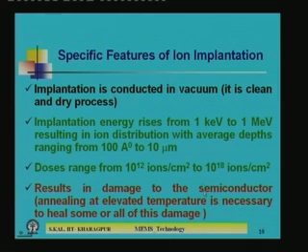During the implantation process, because of the damage, the material may be amorphous in nature. How do you know it? Just after implantation, if you go for measurement of the sheet resistance, you cannot measure it because it is amorphous in nature. But after annealing, it will be recrystallized, so you can easily get the single crystal layer, and then you can measure the sheet resistance by the 4-point resistivity method. So that is one of the reasons why, just after implantation, you cannot measure it.